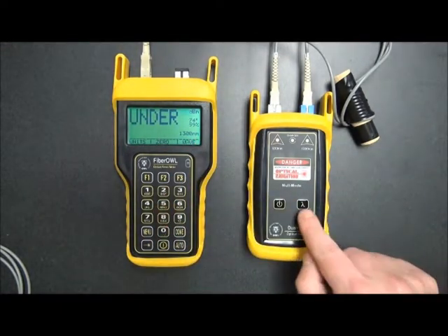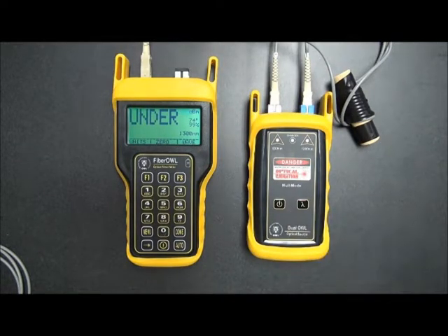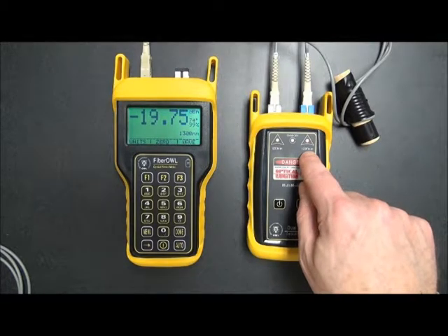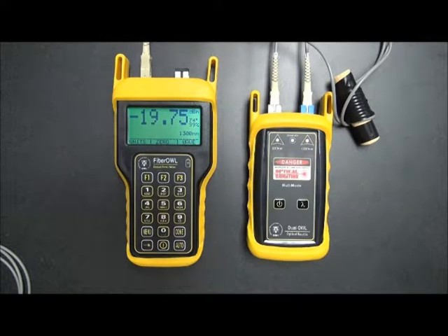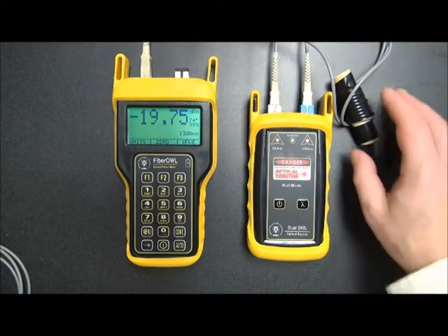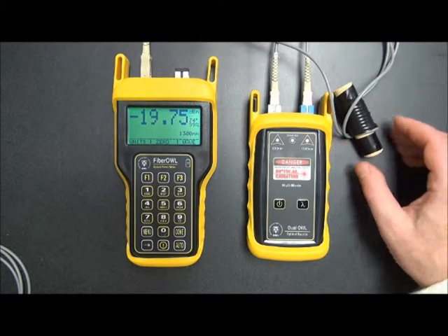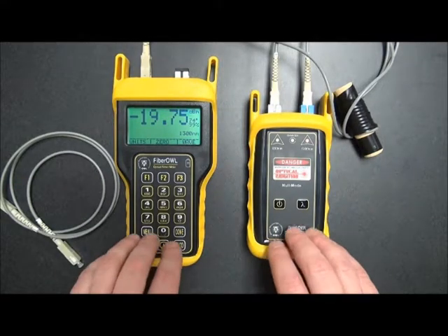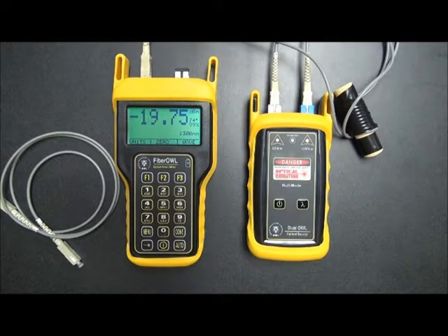And then we also press the wavelength button on the light source. Okay, as you can see, the indicator LED is now lit here. And we have a reading of around minus 19.75. Again, this is very close to minus 20. Even with a mandrel wrapped cable, we make sure that it's not below minus 21 dBm. So both of these reference cables here are acceptable for use for loss measurement. And this straight cable is also good, and we can be assured that our equipment is in proper calibration.